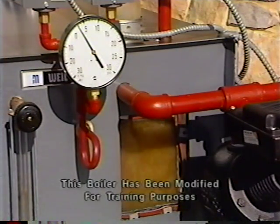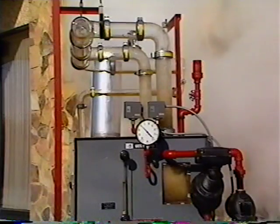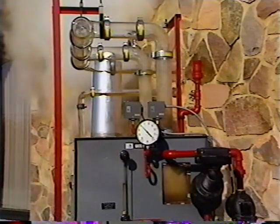Not enough water in the boiler can affect the steaming action, and in some cases will cause major damage to boiler sections and the burner. If the boiler has more water than required for normal operation, surging could occur, forcing water out of the supply tapping into the header and system mains, restricting the efficient flow of steam and creating water hammer.